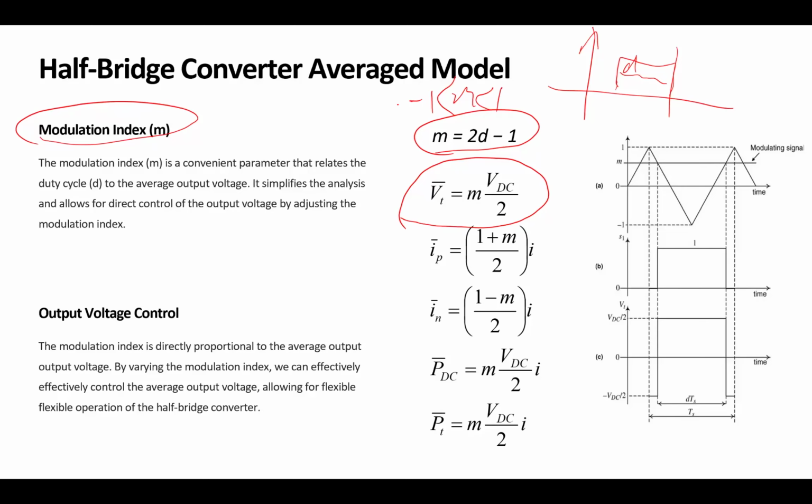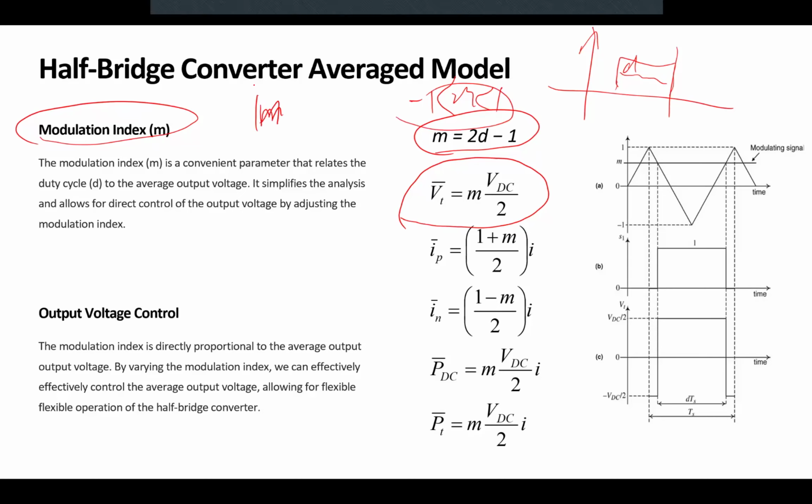If you're chopping down, definitely you won't get anything more than what you had, since you are turning off some part of that. The minus plus part is the phase displacement that you create to your signal, which, to be honest, doesn't matter because we have a continuous AC signal; in power systems it won't affect much. Based on that, for the limit we normally only consider the amplitude of M as less than 1. So this is the significance of that.